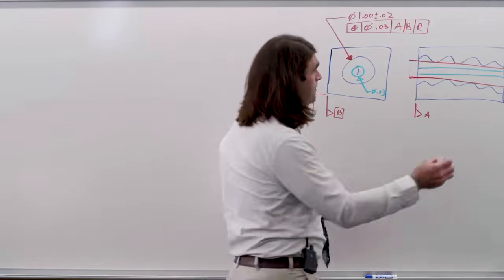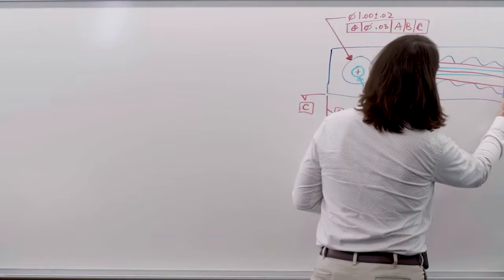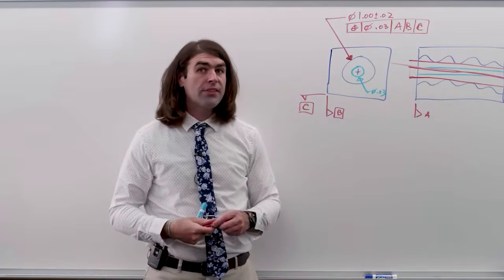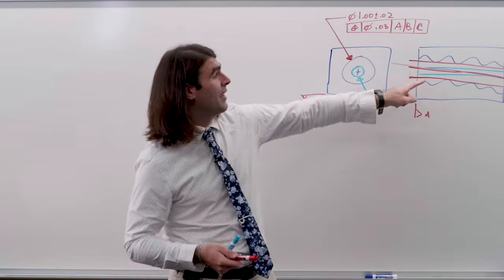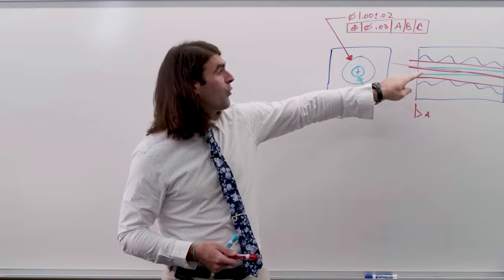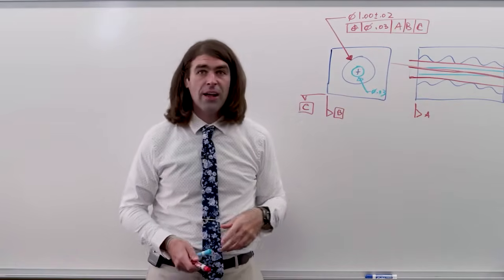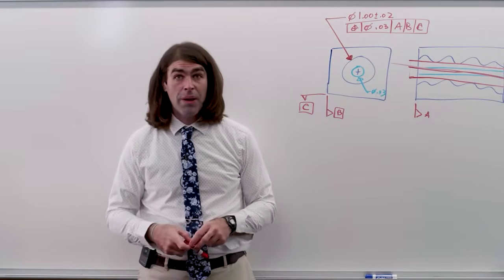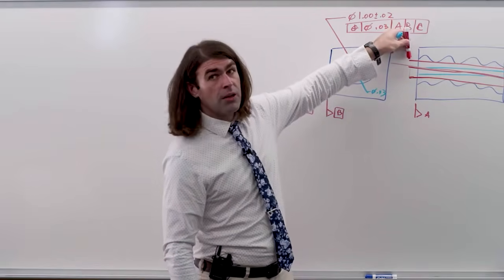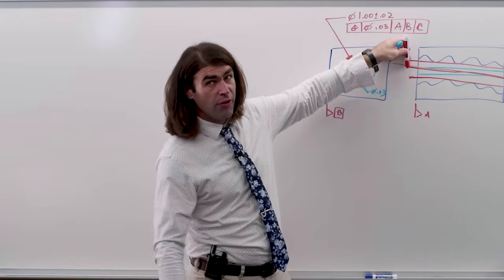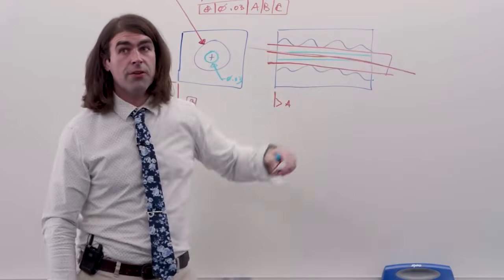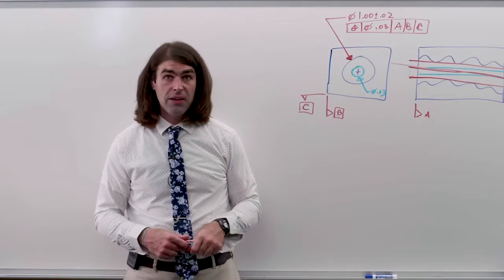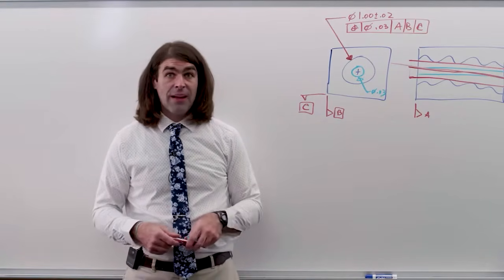So if we imagine, and I'm going to draw it solid, the actual mating envelope's axis is the axis of the feature, and now we're just looking to see if that entire axis falls within the blue here, our tolerance zone. Now, it's really not that difficult to do on a plate, and I've made a whole other video about it. Essentially, you're going to measure from here, take half of the gauge pin, go down, and you'll find a point. You'll do the same thing on the other side. You'll take the worst, do a little bit of trigonometry, which I'll show toward the end of the video, and figure out whether it's within tolerance or not.